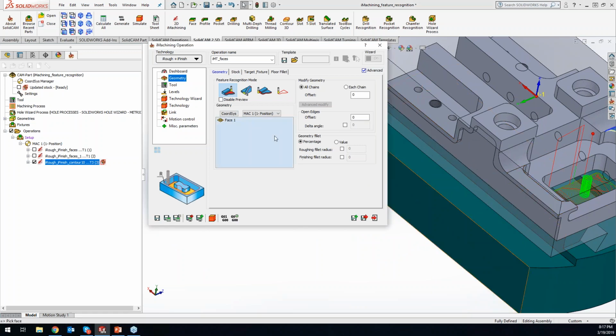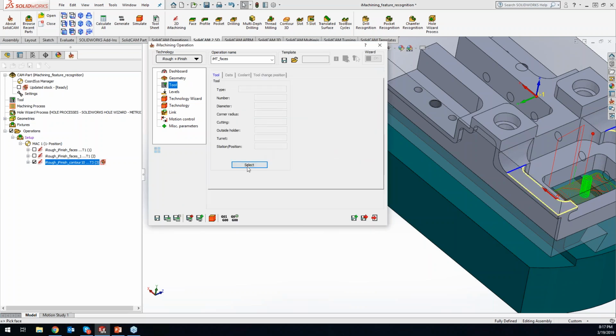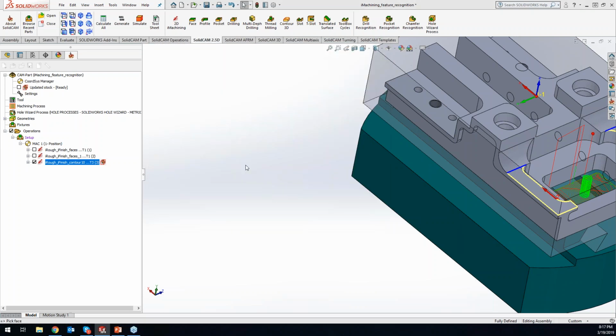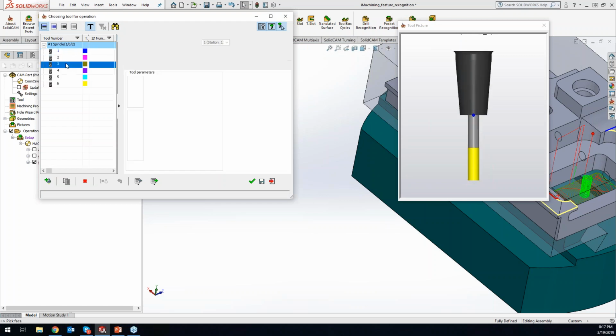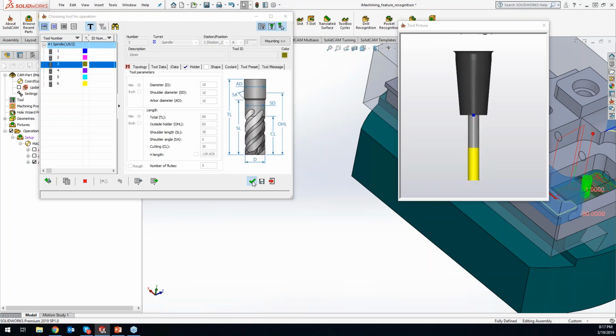And one thing you've got to remember is to make sure this is selected over here, because if we just click on feature recognition and click on the part, it doesn't know if we're trying to do a face recognition or by chain, so we have to highlight it in the field down here to get those faces to pop in there. And it's basically following the same rules that are set up in SolidWorks, where you have to highlight the input box and then make your selections. Yep, great point.